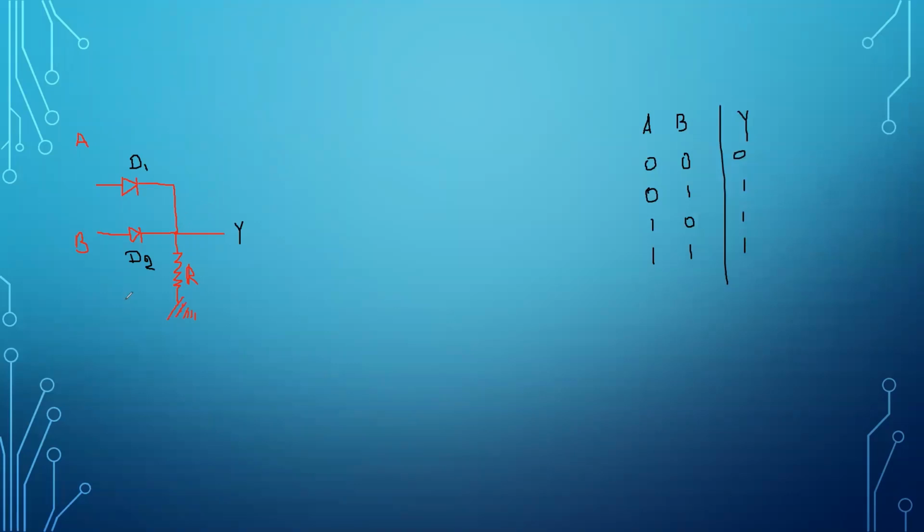So you need to give a voltage higher than 0 to turn on the diodes. But in this case, you are giving the same voltage as ground. Then what will happen? The diode is going to be off because the anode voltage is not higher than the cathode voltage. So here both diodes are off, that means open circuited.